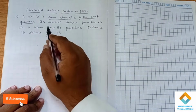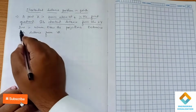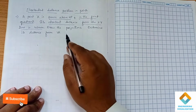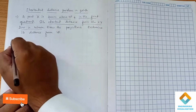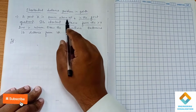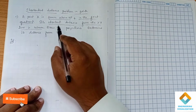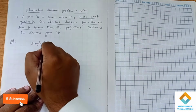And then after that he is mentioning that its shortest distance from the XY line is 40 mm. That means an arc distance of 40 mm you have to consider to construct it, and then draw the projections, determine its distance from VP. Okay, so you all understood, right? In this problem they are mentioning only one view, that is the front view, and then they have given the hint that we have to consider the first quadrant, and then they have given the shortest distance. So shortest distance means arc distance.